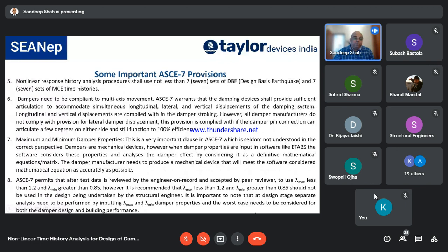Yes, you need to undertake the nonlinear time history analysis for both. You are designing dampers to MCE, then why undertake the design basis earthquake, DBE, right? Now, the reason for this is all dampers are...